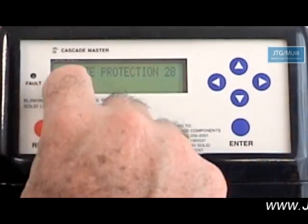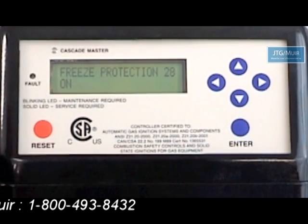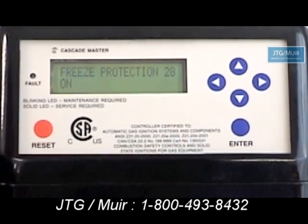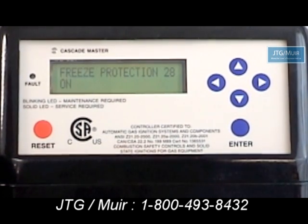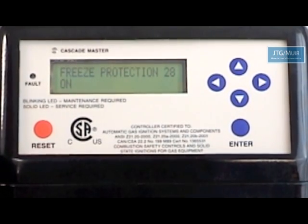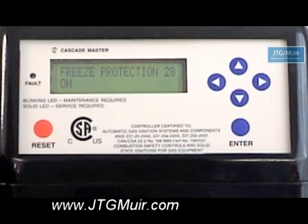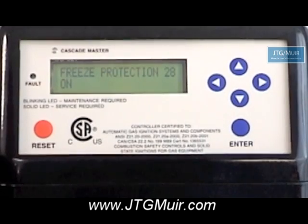Freeze protection. Freeze protection, if this is on and the internal water temperature in the boiler reaches 43 degrees, the circulator in the boiler on the P1 pump will actually come on and circulate water. If that continues to drop and hits 37 degrees, the boiler will actually fire and heat up to approximately 50 degrees. The primary loop prevents any freezing within the cabinet.